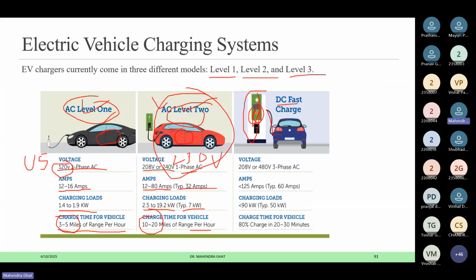As it is outside, you can charge with very high power as well, because if we want high power charging inside, it will increase the weight of the vehicle, and once you increase the weight, the mileage also gets reduced, because that much load has to be carried along the journey. So the battery power will be used to carry that load as well. So generally no one will use a high power charger onboard in the electric vehicle. High power chargers will be available outside only.